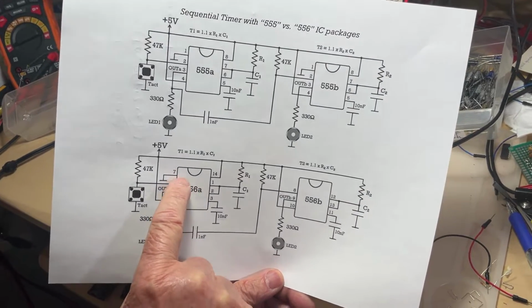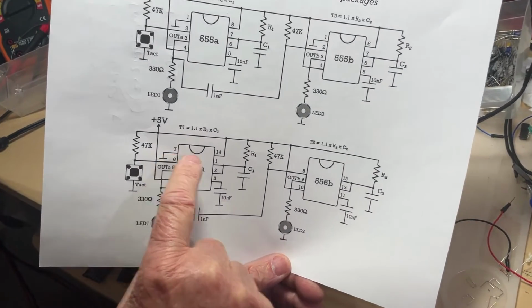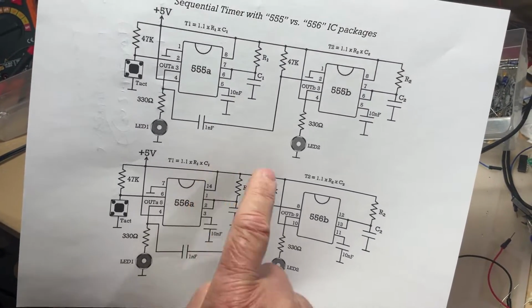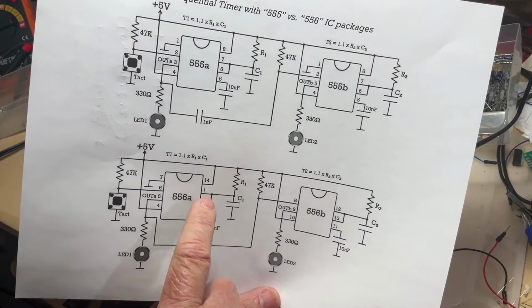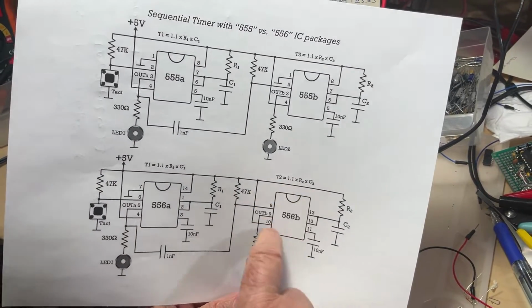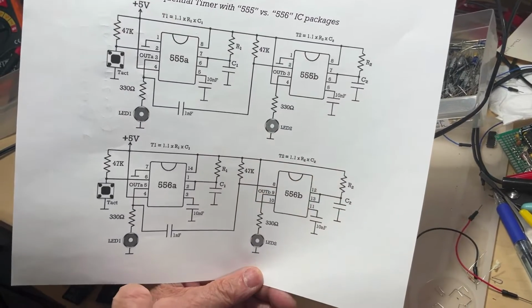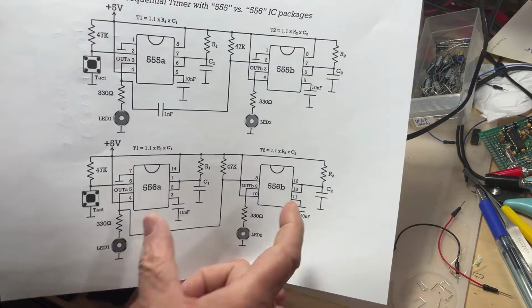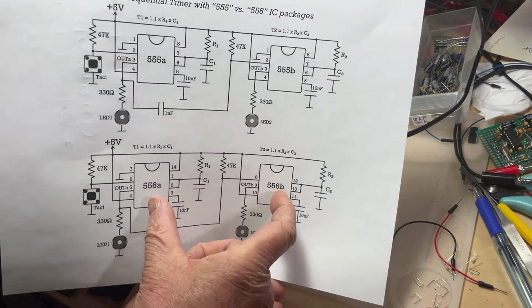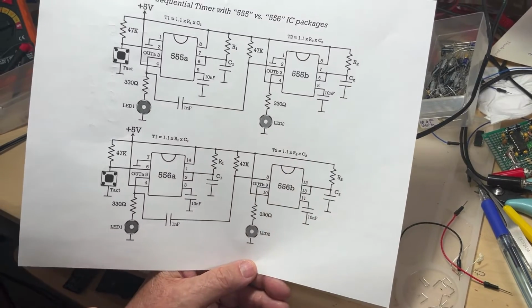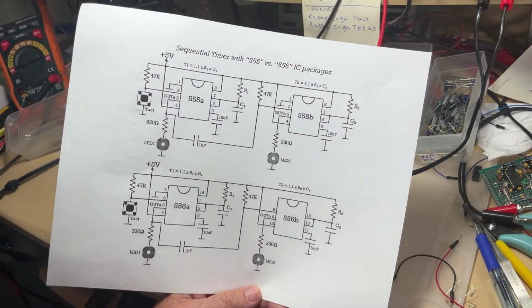As you can notice, the pin 7 is now the ground, and pin 14 is the plus voltage, the positive voltage. And here in the experiment, I'm going to use 5 volt. On the second half of the package, there is no more connection for the pins of the supply because these two share the 2 pins of the power supply together. So you only have the functional pins for the connections.